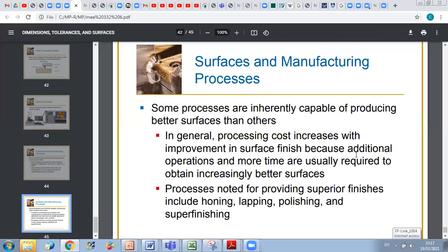And finally, super finishing, also known as micro machining or micro finishing, is one of the most accurate smoothing processes. It is achieved by removing just a thin amorphous surface layer left by the last process with an abrasive stone or tape, and this layer is usually about 1 micron in magnitude.